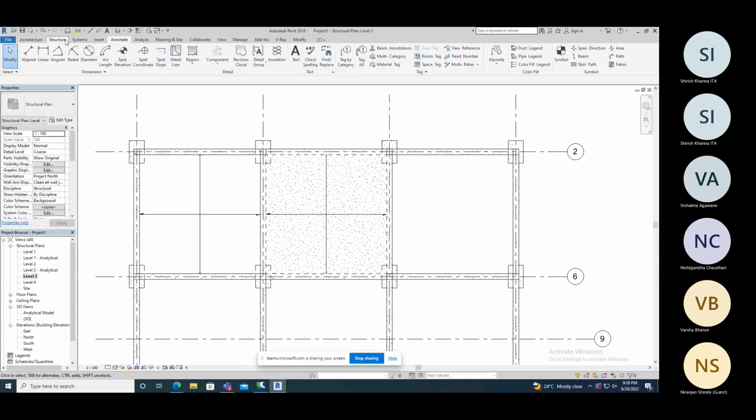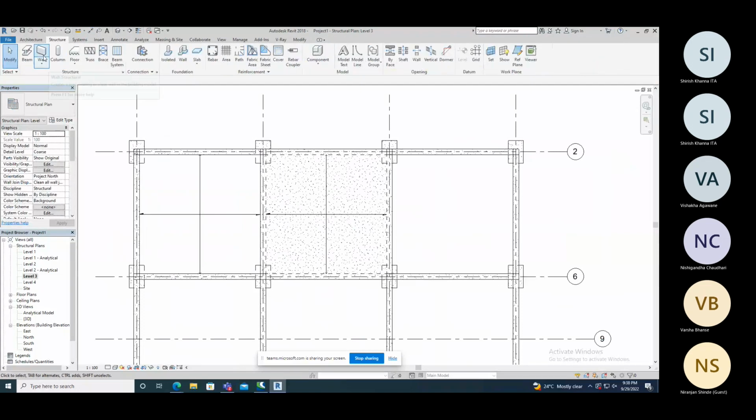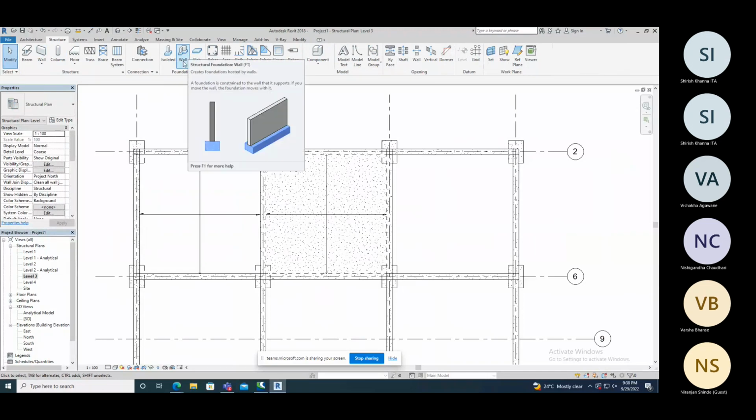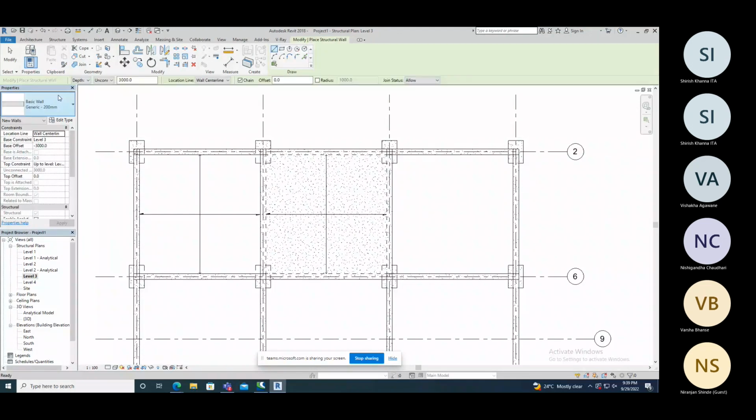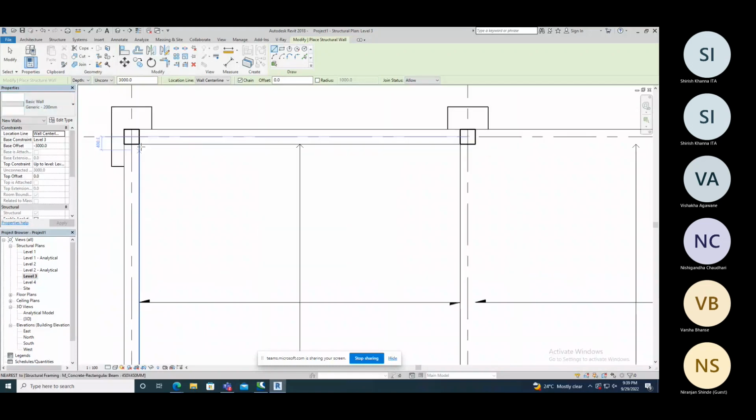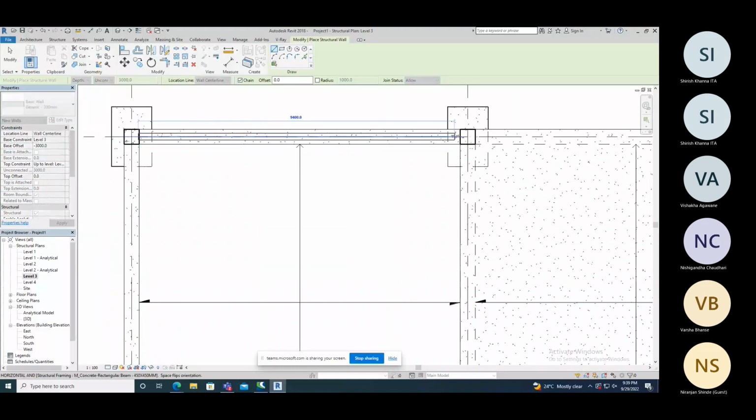So we have available here two types of wall. Here wall and foundation wall. Foundation wall having only concrete one. Okay. And it's having some footing also. So right now we need only wall. Just close it. I'm using here simple structural wall, the basic general wall. Okay. And I want to create it here from this column to this column. But what is the height of it?